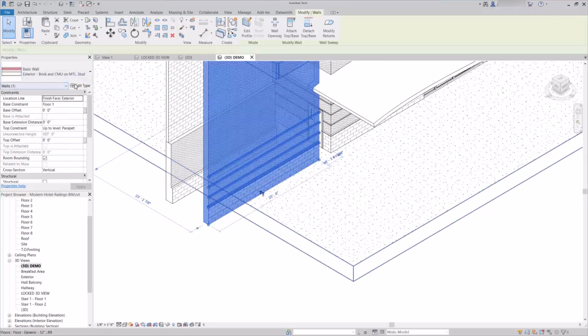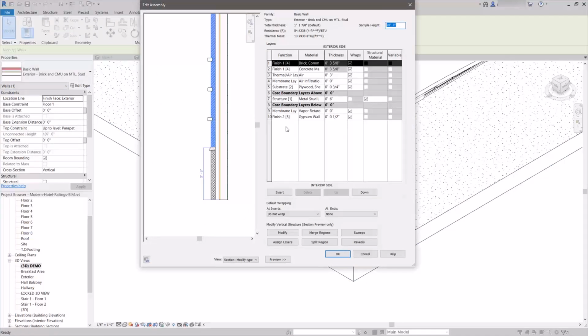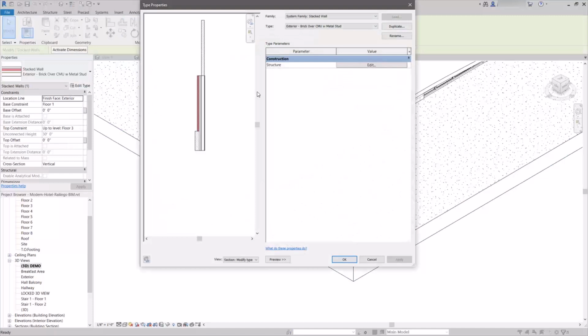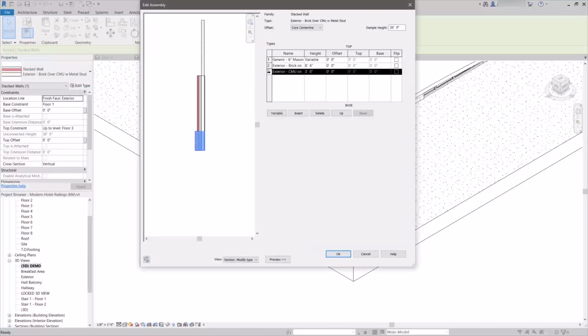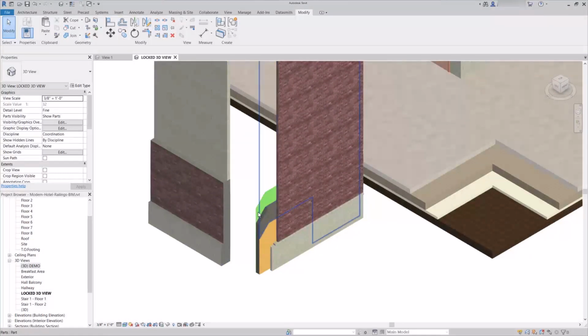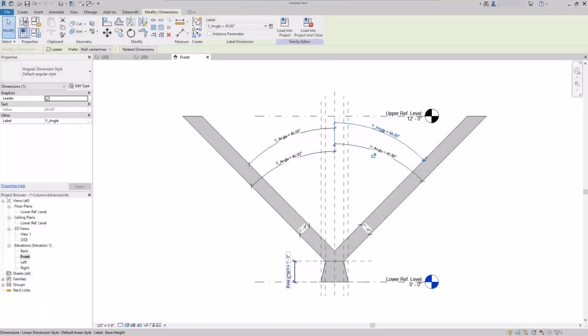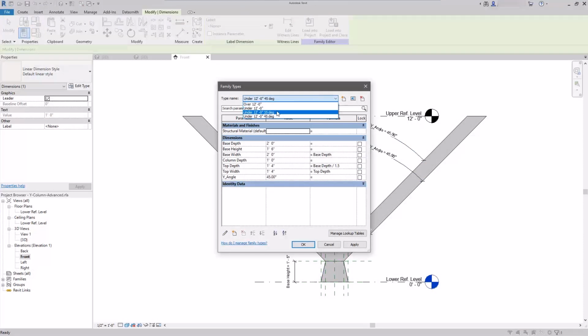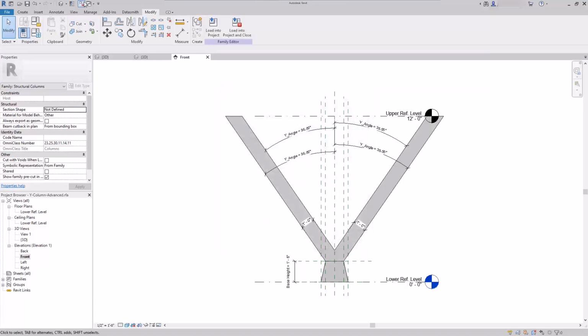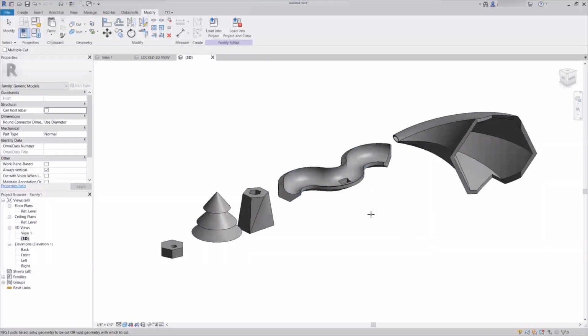Completion of this one-day course will enable students to discover how to create system family types for structural walls, floors, and roofs, modify wall types vertically to include split materials, profiles, and reveals, create a vertically stacked wall type from more than one wall, understand the different types of families that can be created within the software, set up a parametric framework using reference planes, dimensions, and labels, flex the framework to test that each parameter functions correctly, create solid and void form types, including extrusions, blends, revolves, sweeps, and swept blends, create different family types for change in material and size, and load and test the families within the project.